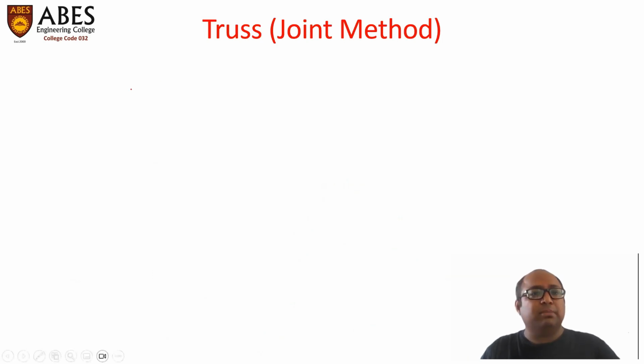Before we find the force in member BC, there are a few assumptions we normally make. I am making an assumption which is important for you to understand: that we want all the members to be in tensile load. I am assuming that all the members of the truss are having tensile load. And then we have to find the reactions at the support.